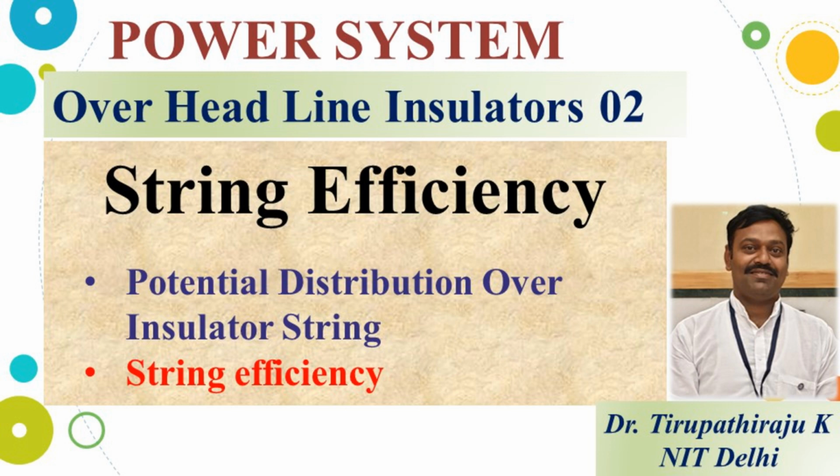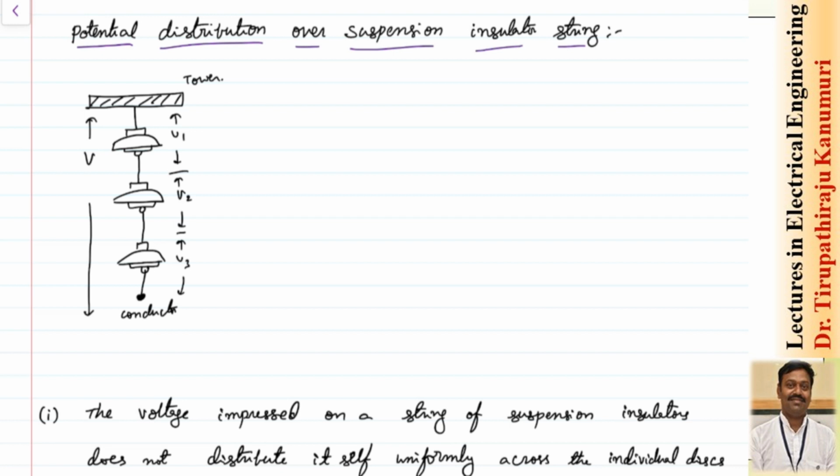Hi all, today we are going to discuss string efficiencies. We know that if you are going above 33 kV, the pin insulators will not be efficient. So we go for suspension insulators. They are called suspension insulators because the insulator is suspended from the tower. That means they are oscillating or hanging from the tower.